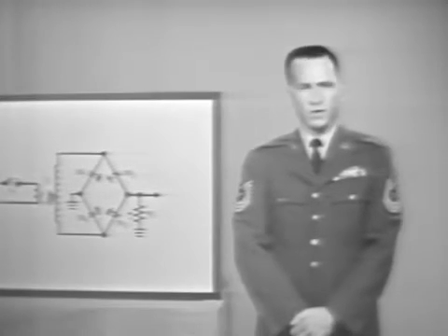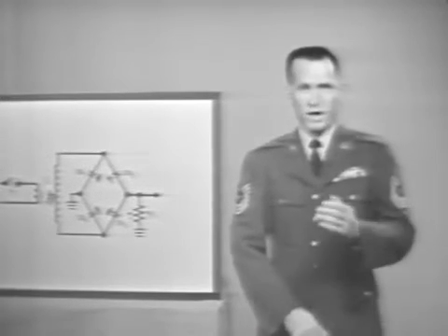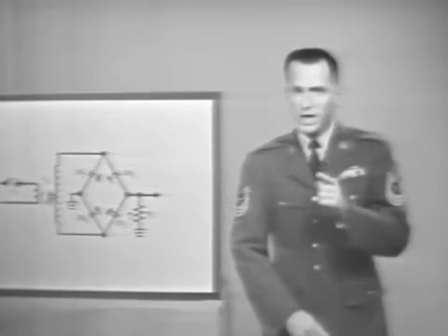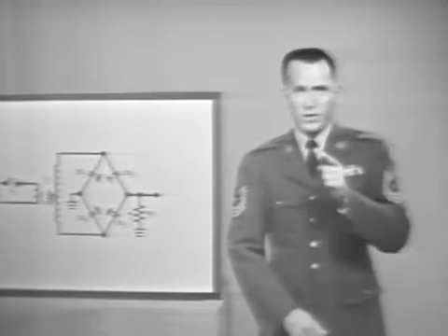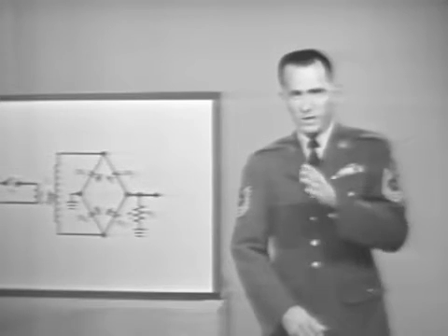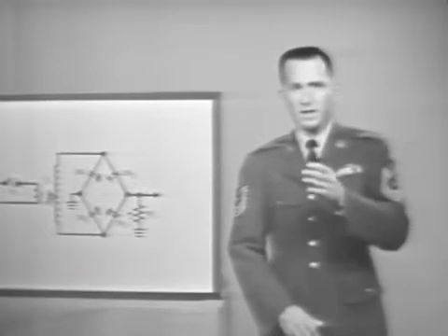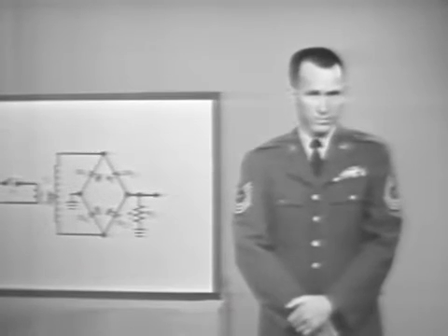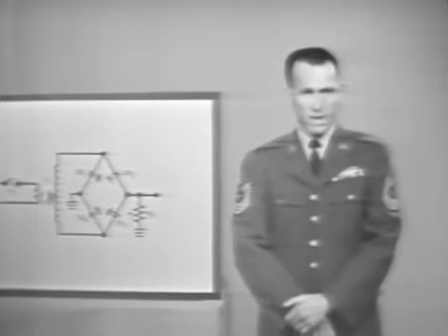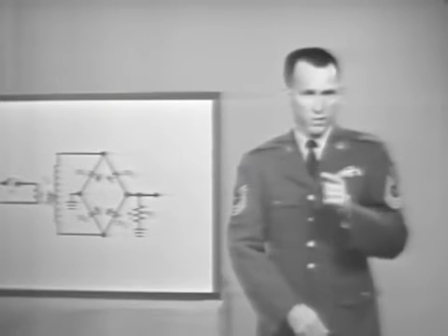The second point to remember is this. When converting from primary voltage to secondary voltage by multiplying with the step-up ratio, the secondary voltage only changes in amount. Now, if the input is given in its effective value, then the secondary voltage will also be in its effective value. If the input is given in its peak value, then the secondary will be determined in its peak value. So the first thing to do in calculating any voltages in the circuit is to use the transformer ratio, if any is indicated, and then determine the secondary voltage.